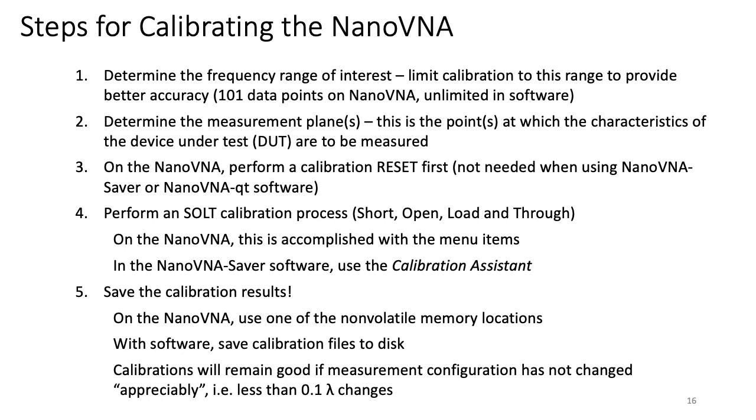These devices, short, open, and load, are usually provided with the Nano. The NanoVNA-H, for example, has a set of SMA connectors where one is a short circuit, one is an open circuit, one is a 50 ohm load. And there's also a barrel that is used for through measurements, and that's attached between the cable runs from the single port that generates the output to the port that's accepting the input, port 1 and 2.